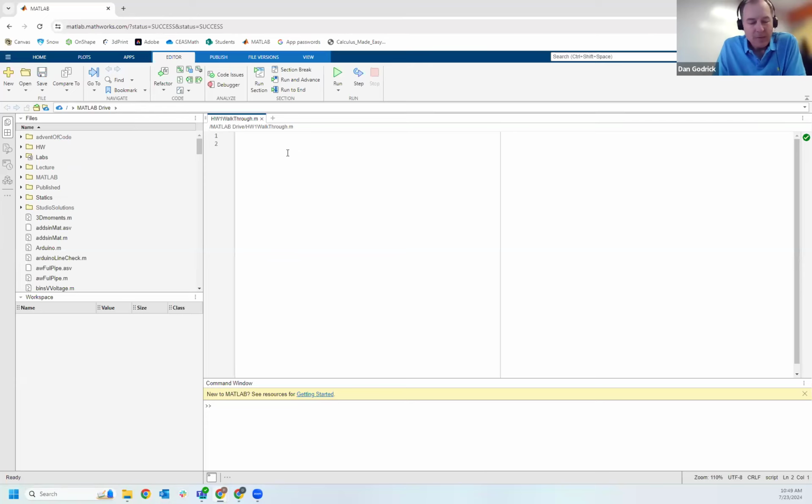And remember from last time, there are actually 4 commands that we like to have at the start of every script. First we use clc, which clears our command window. Then we say clear all, and that clears our workspace. Then we say close all, and if we have a figure, it'll close that. The other thing we know is that MATLAB has weird formatting for its numbers.